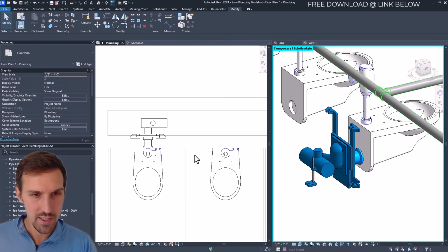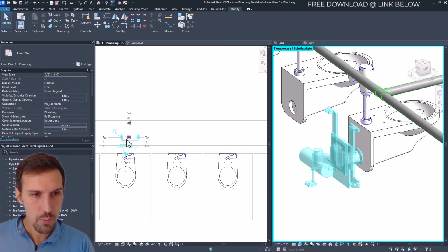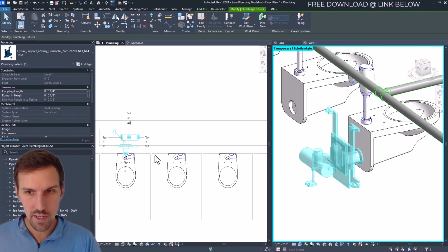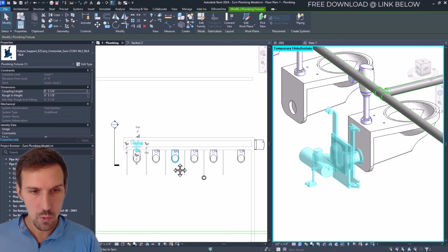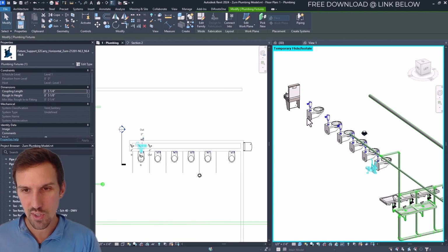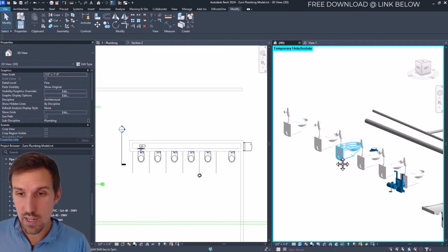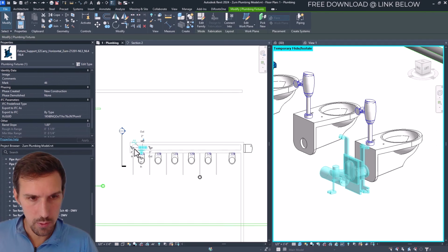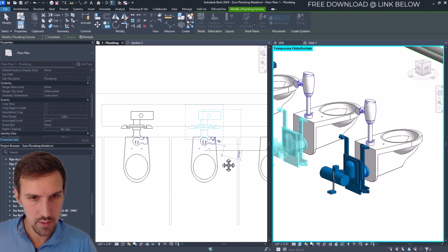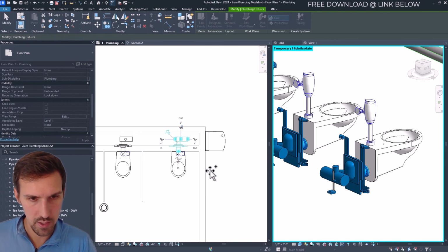All right, so let's continue on. Now remember, we have all of these toilets, and now that we set the height correctly for this carrier, we can go ahead and just copy this along. Now it's up to you whether you want to slope this piping, but usually for carriers, I'm not going to really slope the piping. If you're going to do an as-built that's like LOD 500 for the contractor, then you might want to. So in our floor plan, let's just go to the copy command, and we're just going to go ahead and copy all of these over just like this, just using the copy command and clicking.